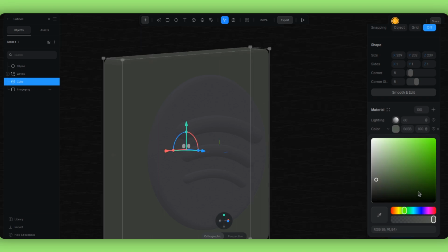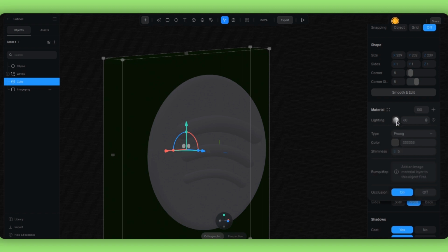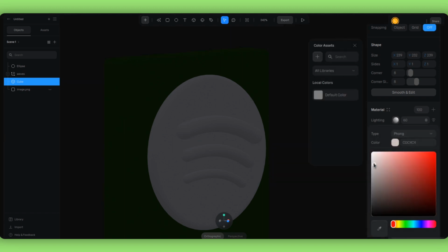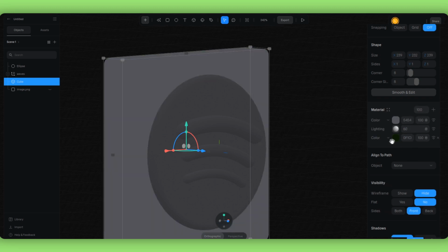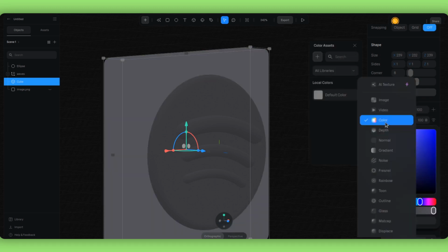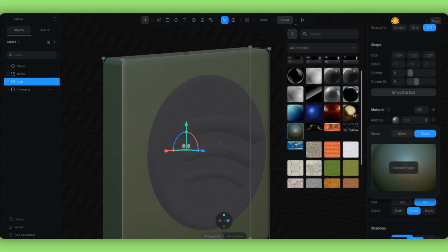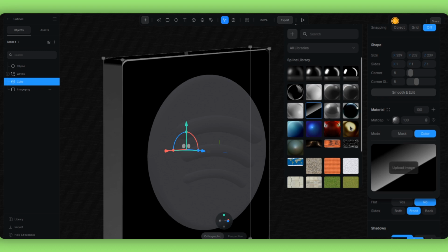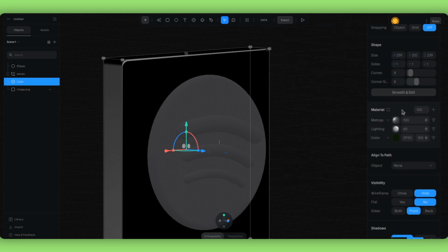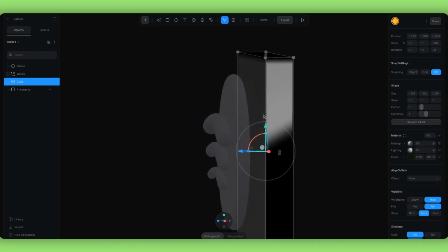And to achieve that effect, we are gonna use 2 layers. One is gonna be the base layer, which will be the dark green color. And we are also going to add the matte cap layer, which will give it the shining effect. Spline has a set of default matte cap options that you can use to add the shining effect. There are a lot of them, and any will do the job. I went with this one that has a line because I think it looks better for the backdrop.